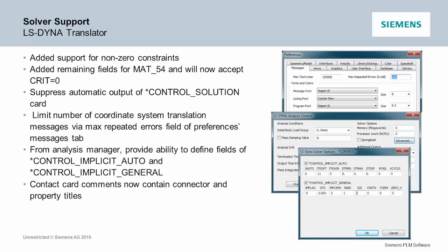We've added some Dyna stuff. Again, this is actually kind of launch control and setting up the jobs and getting them running, and then we continue to add material property support. We've also added a user-defined material for Dyna where you can set up any Dyna material. You just tell it what the keywords are, what values you want. So now you can actually handle any Dyna material. You can kind of code it up yourself.